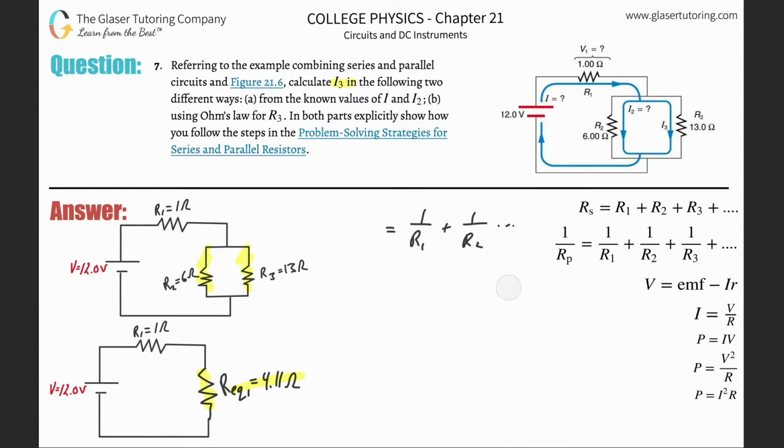But now, it's not totally simplified. Now you want to ask yourself, well, how are these two resistances related? Are they connected in series or in parallel? So just trace your pen or pencil or whatever, your finger across the screen. If you flow through this resistor, you don't have a choice but to then flow through that second one, right? That's series. That's all it is. They're connected in series. The current has no other way to flow, okay? So now I know these two resistances are connected in series. And therefore, I can now find an equivalent resistance between the two.